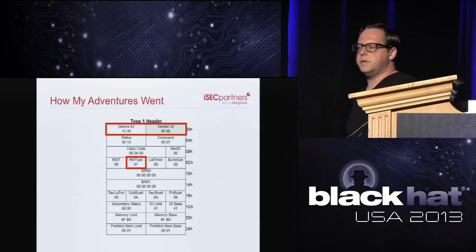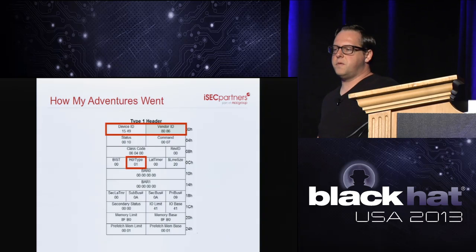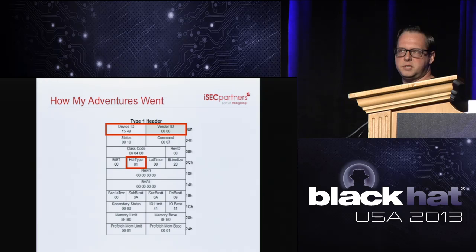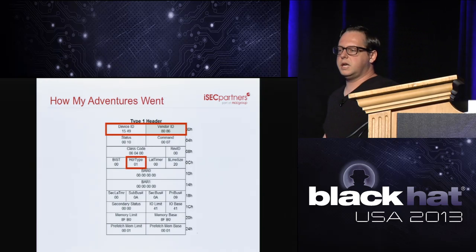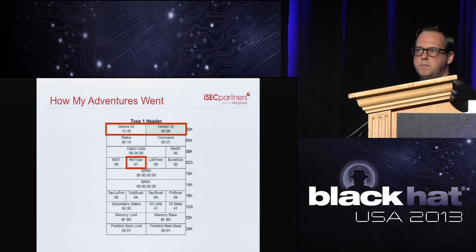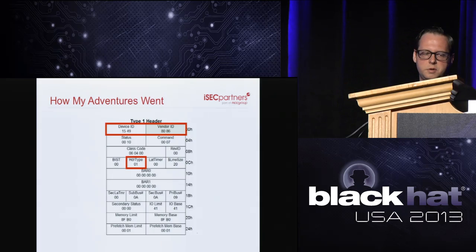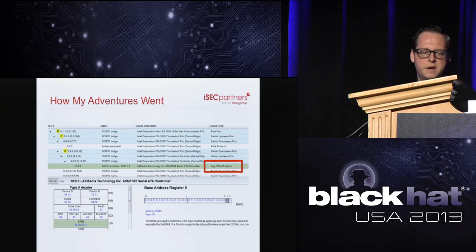Looking at the PCI Express header for this device, we see 1549 8086. Those bytes we were seeing earlier are directly related to the PCI Express implementation. So 1549 is the device ID, and 8086, which makes sense, is made by Intel, the vendor ID. So those chips earlier are those bits that went across the wire. Those are PCI Express identifiers.